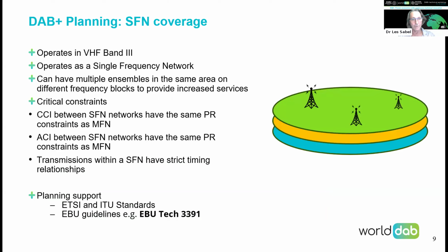So that's how the design of the networks needs to be taken into account. You can't have signal overlapping from an adjacent co-channel out from a different license area into your license area, which is more than that value, that 24.5 dB microvolts.